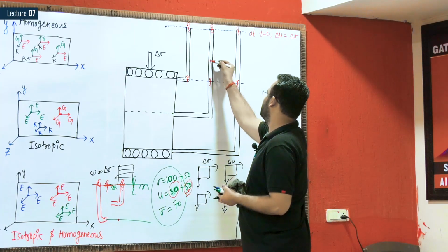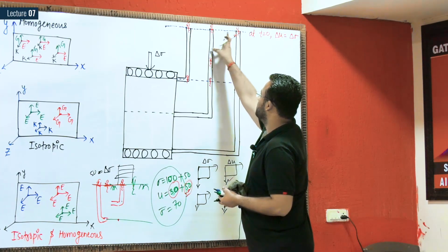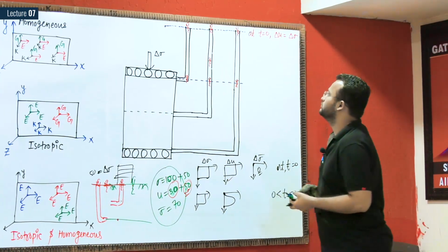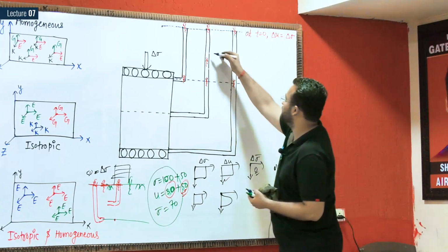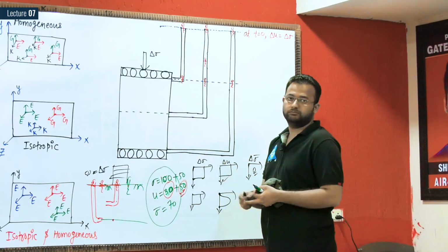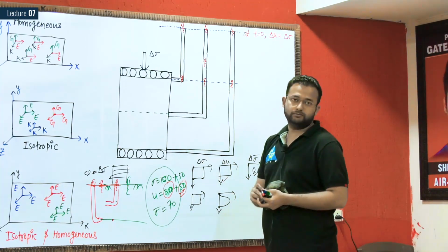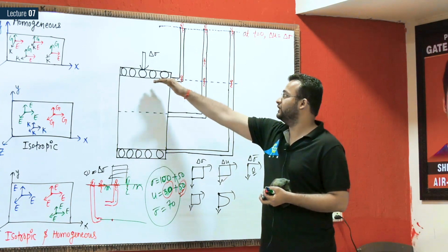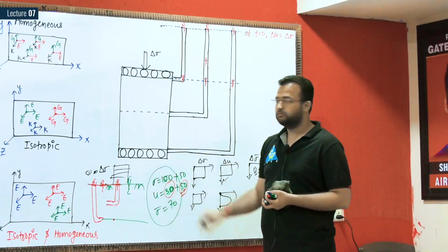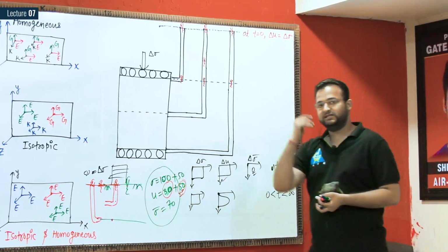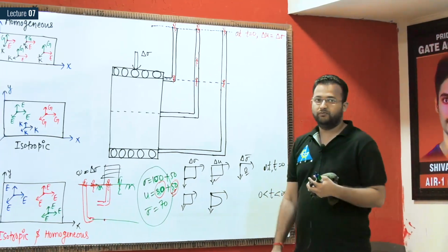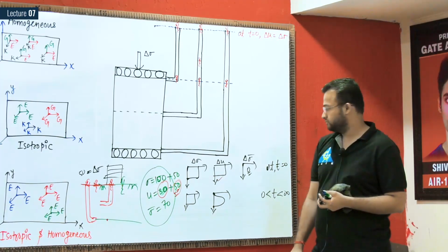Up to somewhere here. Means your water initially was here at T equal to 0, now it has been dropped somewhere here. But if I insert the piezometer here, we are getting the water table here only, because from here excess pore water pressure is dissipated. If I insert the piezometer here, from here also excess pore water pressure is dissipated. So here also you are getting the same level, the old one, when the load was not applied.